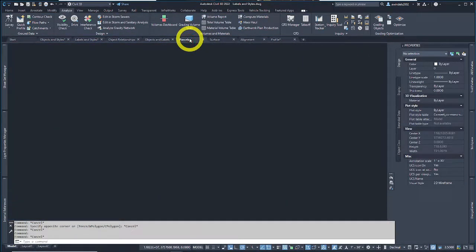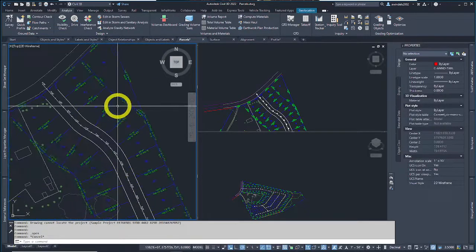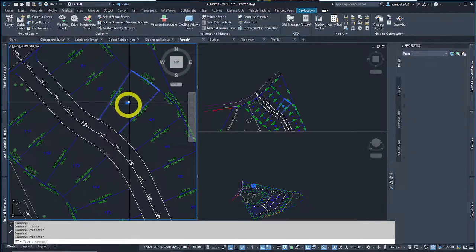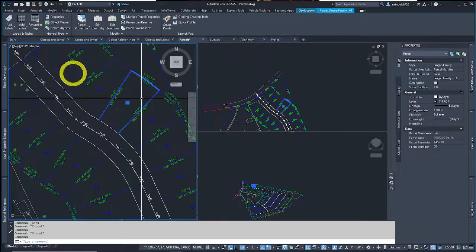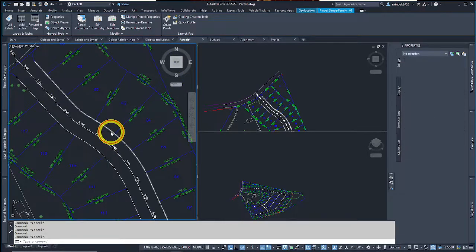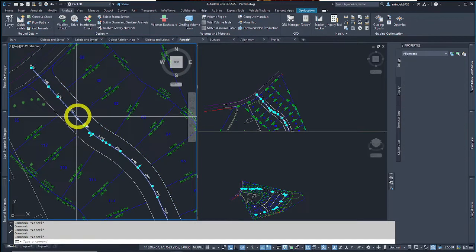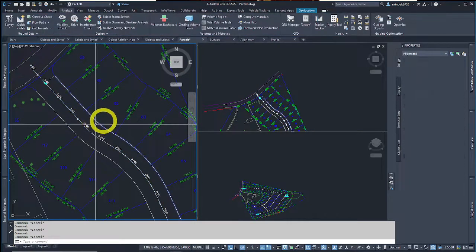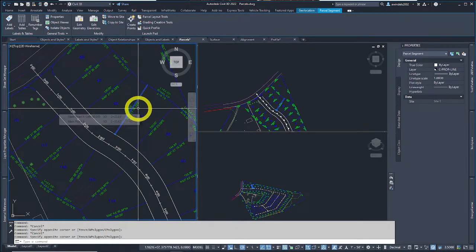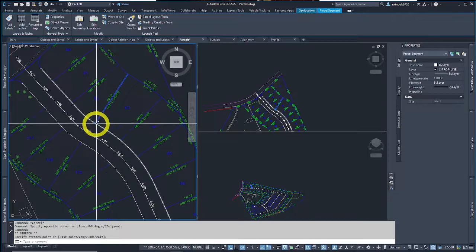Another one would be, if we go to another drawing file, just bear with me, parcels. These are Civil 3D styles built with very specific geometry, these land divided parcels. So if I pick on this lot or parcel number, I have a parcel selected. This is a Civil 3D entity that interacts with other Civil 3D entities. This is an alignment, an offset alignment. Here is a center line alignment. This center line alignment is offset this amount to make an offset alignment. These parcel lines hit it at a certain angle, and they're all interactive with each other. And this parcel line can be moved along this offset alignment dynamically with grips.